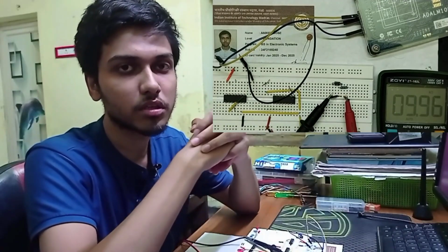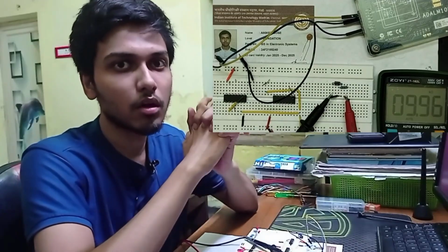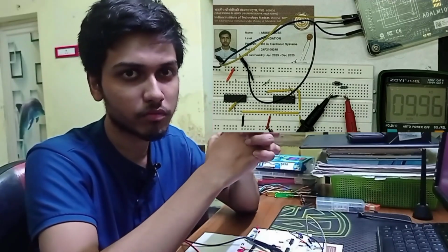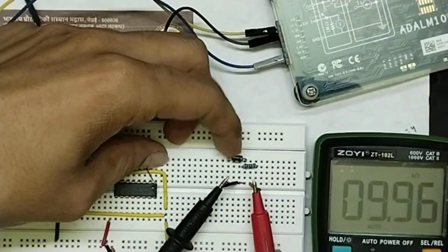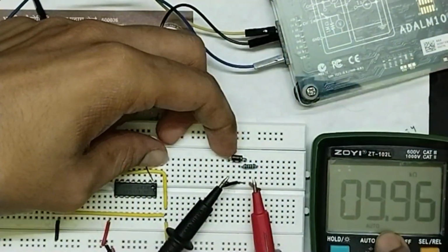In part 2, we are going to study the input and output voltage waveform of a half-wave rectifier. What a half-wave rectifier does is take input voltage waveforms of sinusoidal nature and transform them in the output to DC. Now to do that, we have taken this diode and resistor in series, and the resistor, as you can see, is 10 kilo ohms.